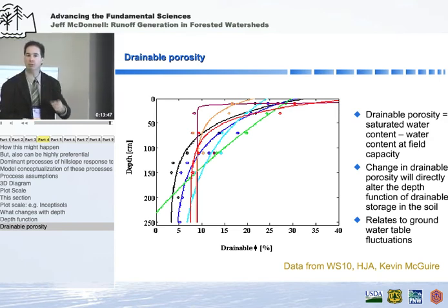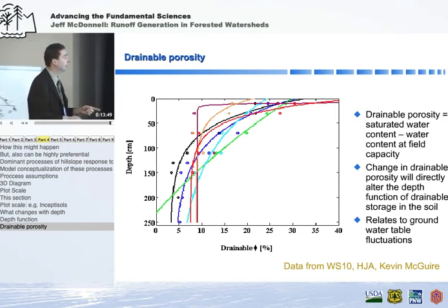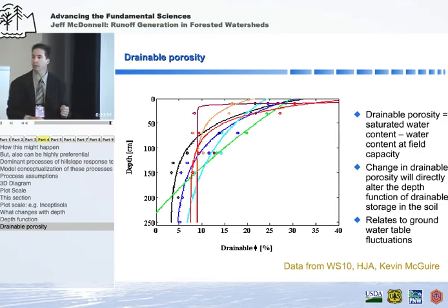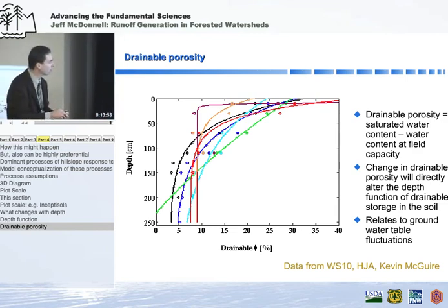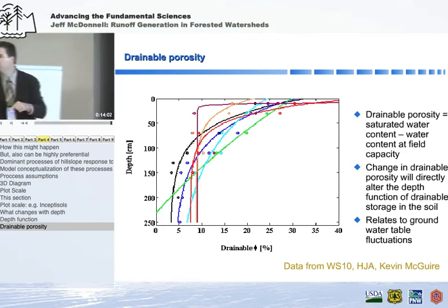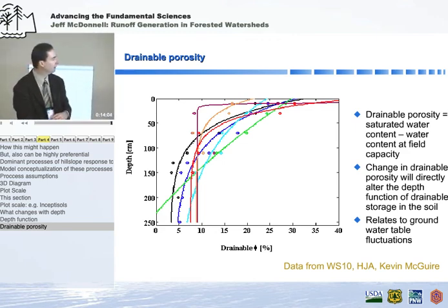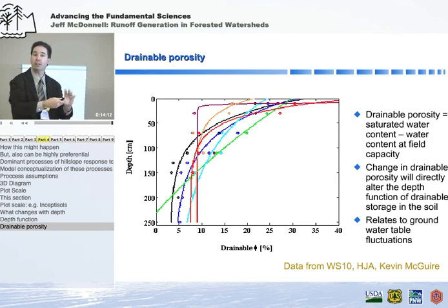This is where preferential flow, that we'll talk about after the break, becomes critically important. Because if we have some preferential flow pathway to get water from the surface down deep, we only need a little bit of water to penetrate along a decayed root channel, an animal burrow, or something to bring this area to saturation. And that's why often water tables develop very flashy at depth.